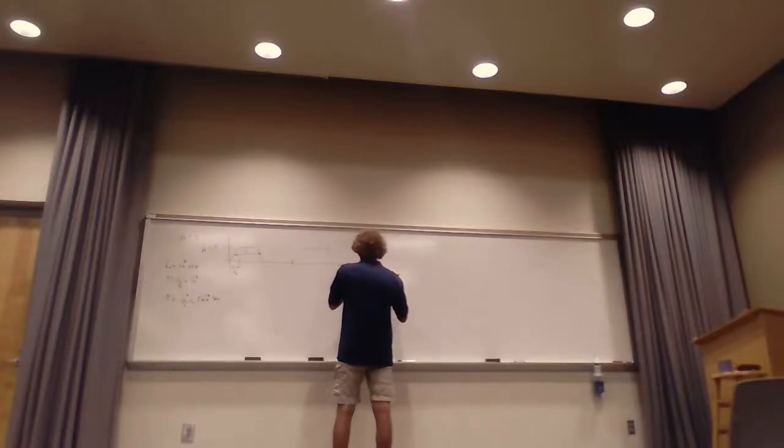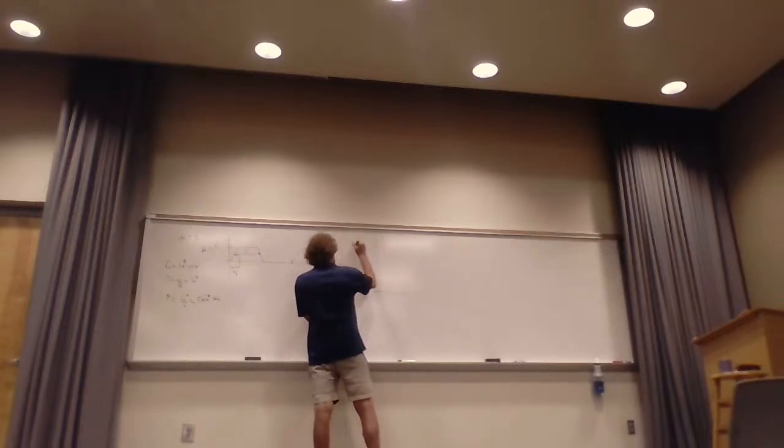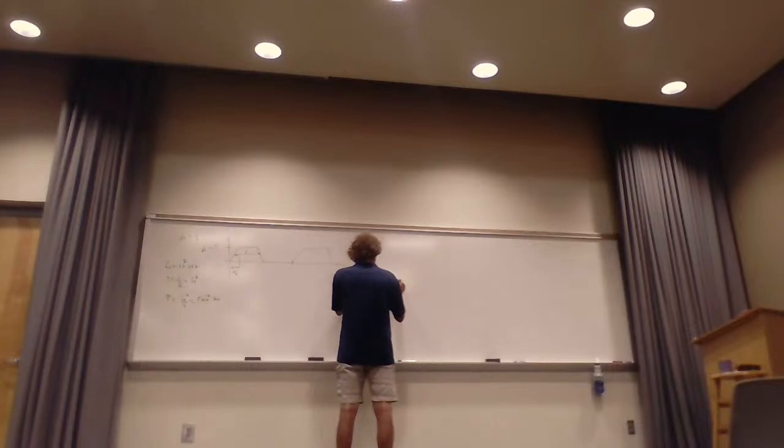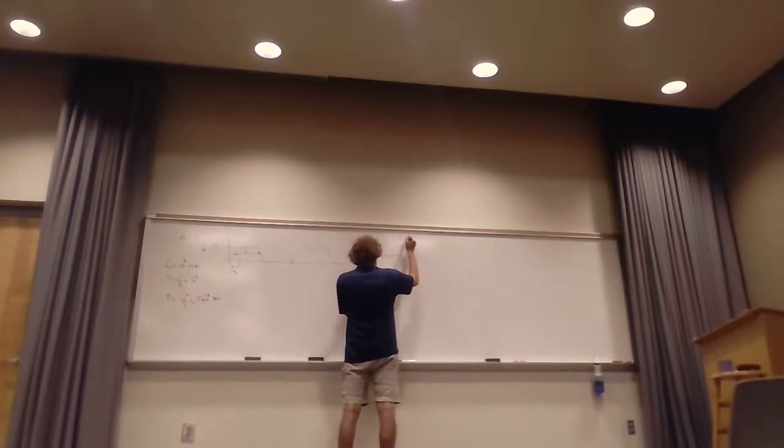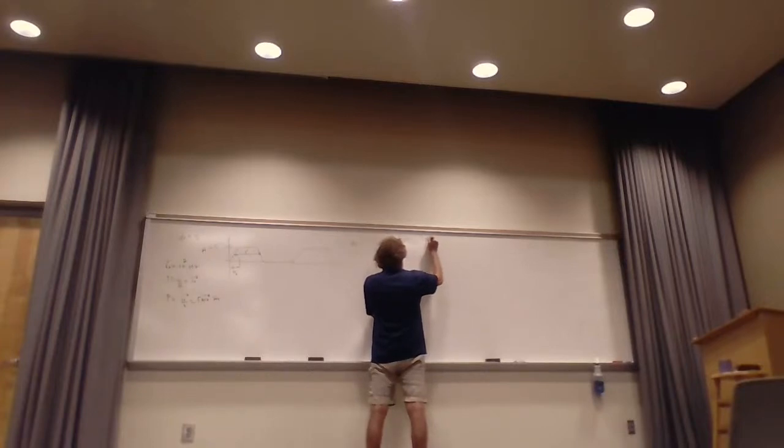So if you're doing this right here, the first thing is when we look at just the source itself, we start out, and this value here is 20 times the log, that's a base 10 log, of 2 times the magnitude of A times tau over the period, divided by 10 to the minus 6, because it's going to be in dB microvolts.